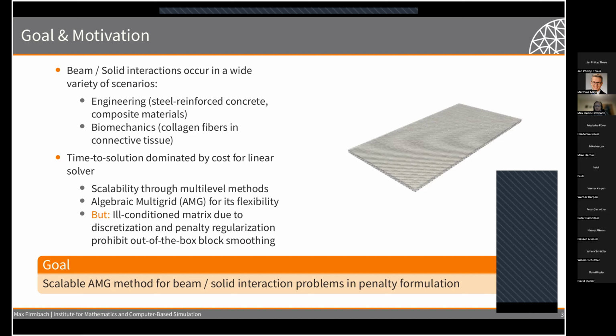And of course, we want to improve the solution time by switching to multilevel methods that are hopefully scalable. We will use MueLu and thus algebraic multigrid methods for its flexibility because it's purely algebraic. So we only have to put in null spaces and our system matrix or system operator.